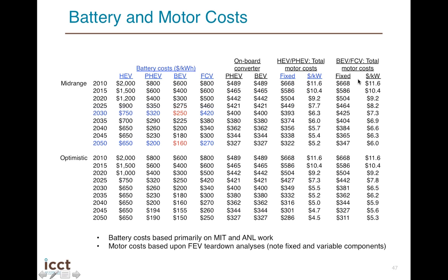The battery motor costs, I'm not going to go into those except to note that most people in the past have assessed motor costs only on the basis of dollars per kilowatt. When we looked through FEV teardown analysis of batteries and their supporting components, we found that there's actually a large fixed cost that doesn't really vary based on the size of the electric motor. Of course, that will still go down over time with learning, but we did split this into fixed and variable costs.